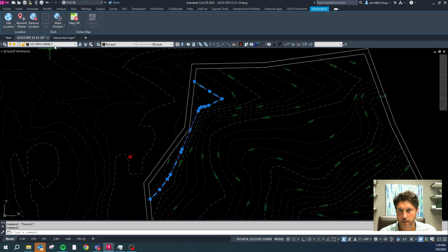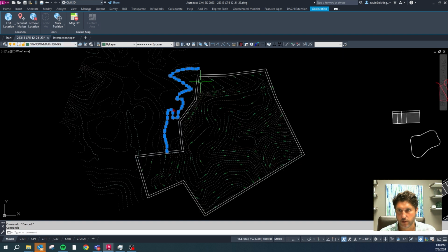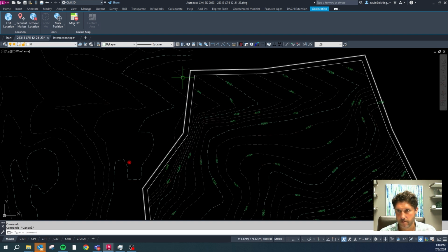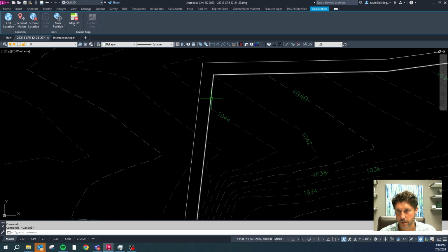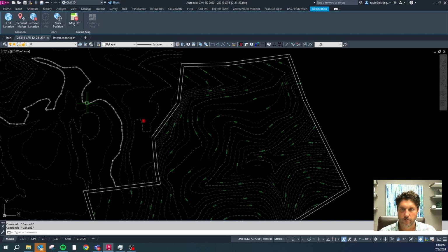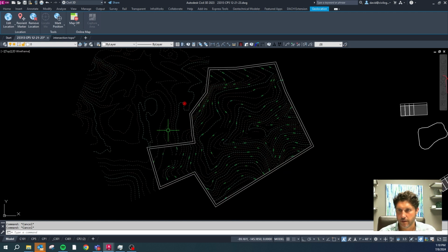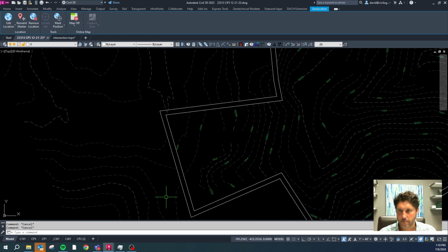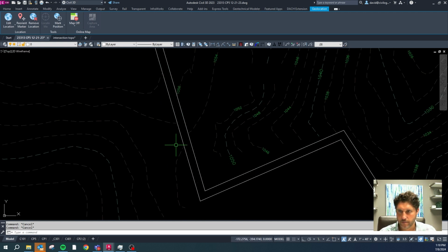This is on the regular layer, and then this was on the GIS layer, so that we can tell the difference between the two. And we have a gap where we're not saying this one goes all the way to there, because we know that's incorrect. There's some gap in here where this one's made off of one vertical datum, that's made off of a different vertical datum, and they're just a little bit different. But we can make some estimates